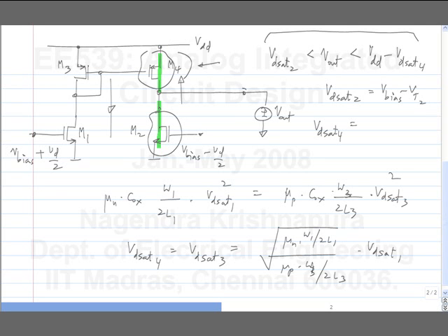If you make the output voltage too high, it could be by connecting a voltage source, or it could be by having an impedance, and the current that is flowing through it will make the voltage very high. Whatever it is, this voltage cannot go higher than VDD minus VD sat of the upper transistor. Okay. So the peak to peak swing that you will get will be the supply voltage you have minus twice the saturation voltage. Okay, or at least minus the sum of two saturation voltages. That is typically the absolute maximum swing you will have. Okay. So as you can see, as the supply voltage reduces, the swing that you have also reduces.